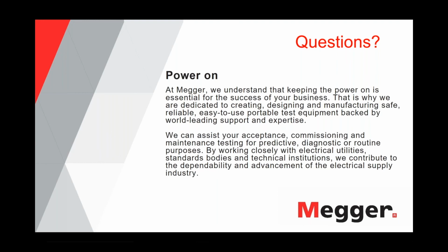That's why it's not recommended to do this with tan delta measurement. We work with some customers who have this. It's a very common situation in downtown networks where you have maybe EPR, XLPE, and paper cables in it. And this is really an application. If you want to do hipot testing or VLF testing, then the cosine rectangular wave shape has a big advantage